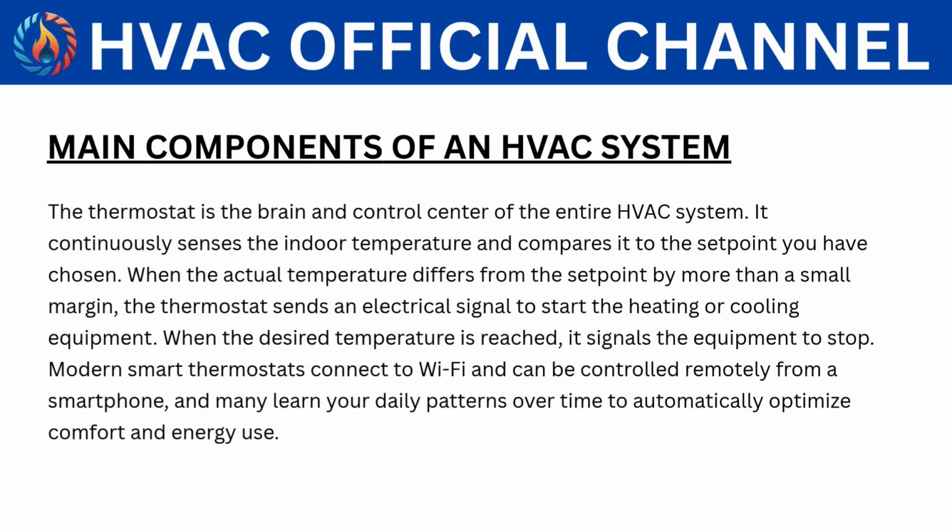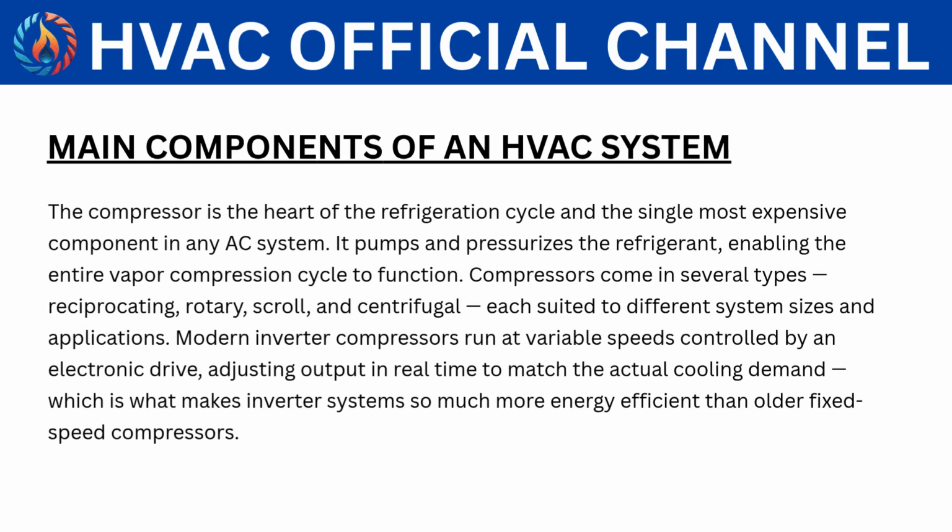Modern smart thermostats connect to Wi-Fi and can be controlled remotely from a smartphone, and many learn your daily patterns over time to automatically optimize comfort and energy use. The compressor is the heart of the refrigeration cycle and the single most expensive component in any AC system. It pumps and pressurizes the refrigerant, enabling the entire vapor compression cycle to function. Compressors come in several types: reciprocating, rotary, scroll, and centrifugal.